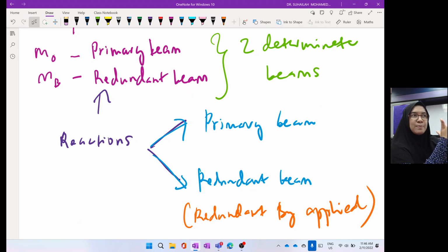And the third step is displacement. So that is the flow. To calculate displacement, we must have the moment equation and internal forces. For thrust, it is the member forces. So remember this step. We apply all these three steps in the flexibility method: start with reaction, followed by moment equation, then displacement. These three that you have learned in solid mechanics and determinate structures are combined in one flexibility method.